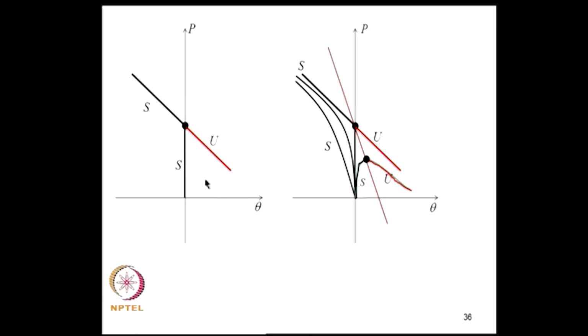Now in the presence of imperfections, the load increases along the load displacement path and again encounters a limit point, afterwards it becomes unstable. There is of course a stable path along which the load can go on increasing, but that is not what governs our design, this branch governs the design.